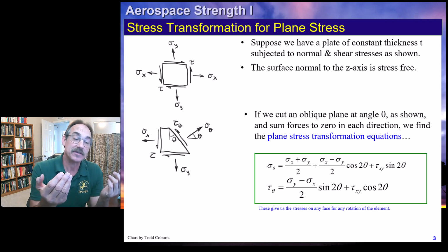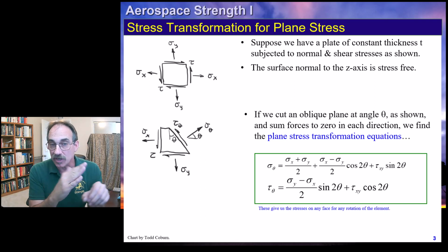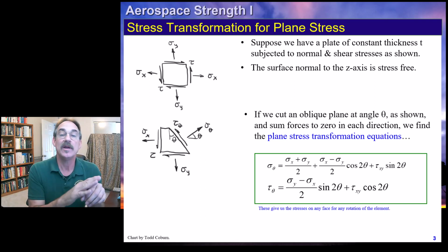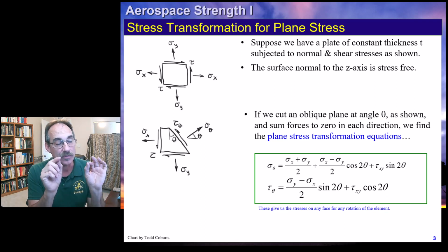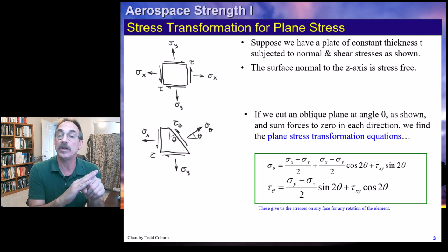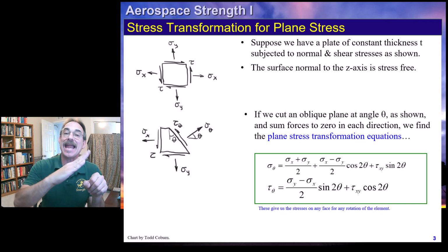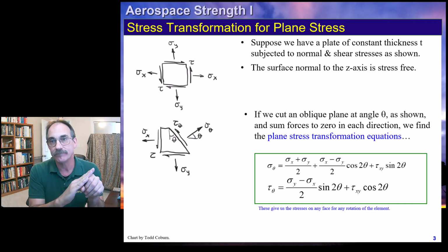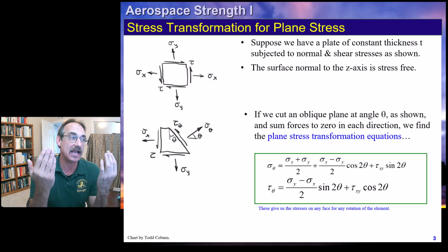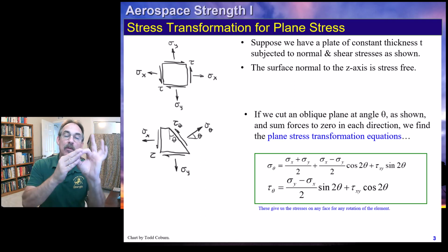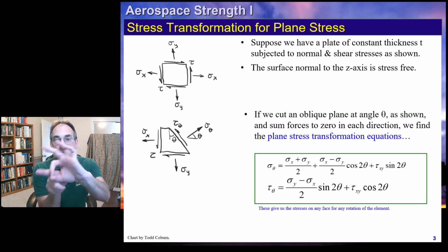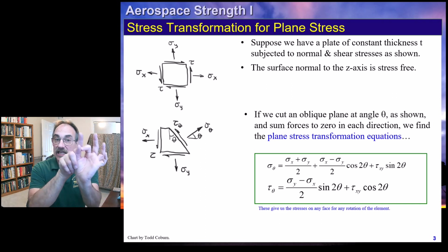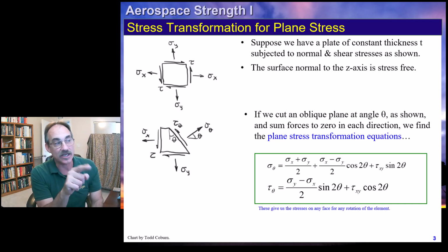We can evaluate this element for the normal stress on that face, and the shear stress on that face. So these equations enable us to figure out how much normal and shear stress we have for any cut through our element. Or, a different way of thinking about this is no matter how we rotate this element, we can calculate the stress on that new x inclined face using these equations.